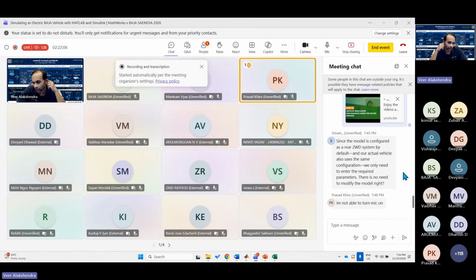That error you got in the battery pack builder, right? Yes, sir. That is happening because of some configuration that you would have taken. It's a common error that people get. What I would suggest is to debug step by step. See how you're modeling from the cell to parallel assembly to module to pack, and at which step you are getting that error.